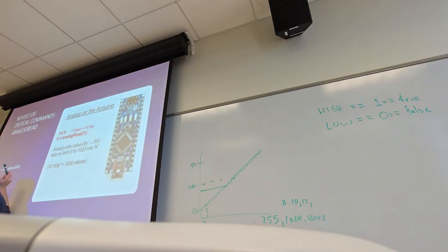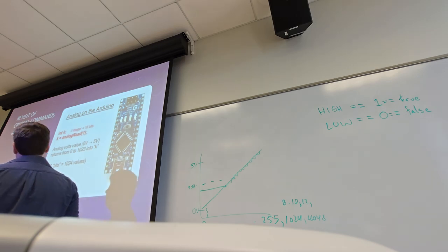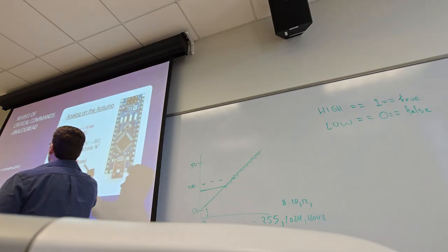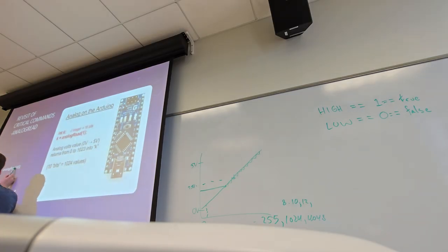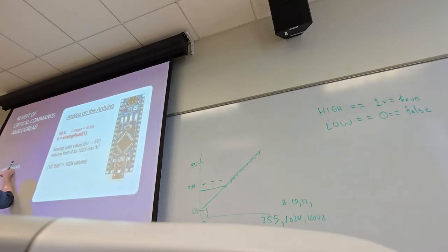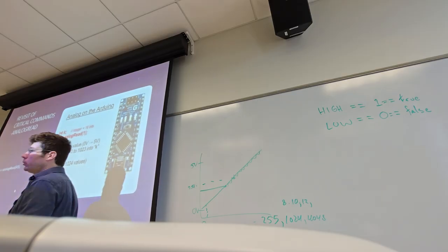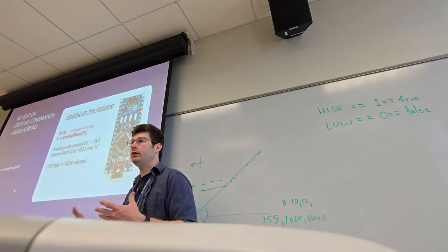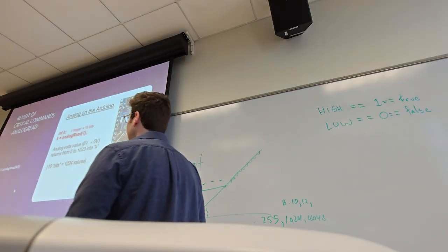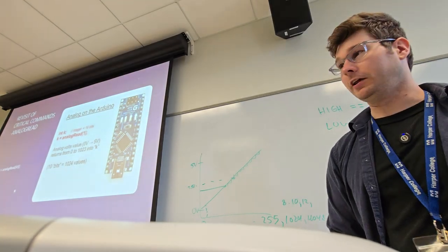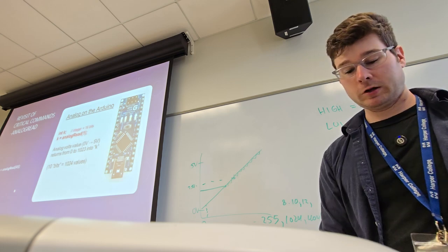So if I had 2.5 volts on my A5 pin, whichever it is in this fuzzy mess, 2.5 volts would read as 127 on a 255 scale. It's half of that scale. And then X would be stored as 127. Then whenever you told it to print, or compare it against some other value, you would compare X to that value, or you would scale it first, convert it back into the thing you're actually interested in and proceed from there.